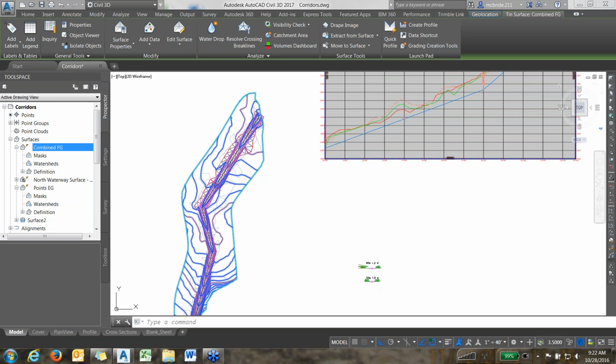The one question that did come up, and I wanted to just reiterate, is even though we're using a parabolic waterway as the base of these last couple webinars, this process of building a profile or proposed grade and then attaching a certain shaped assembly to it to build a corridor to get a 3D cut or fill volume would apply to a lot of other shapes. If this were an above ground feature like a levee, it would be the same basic process.